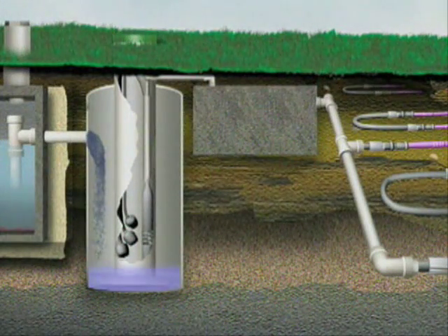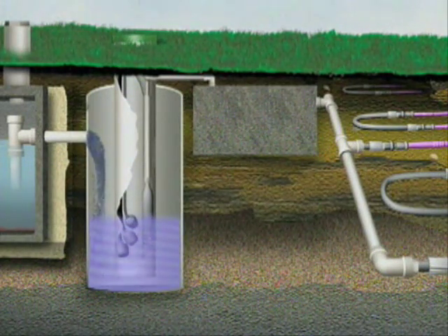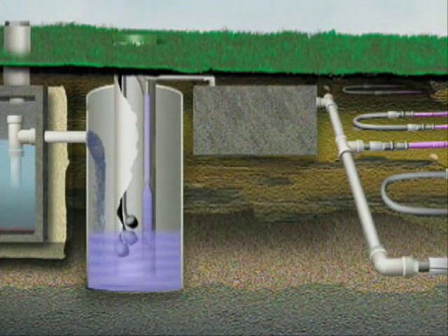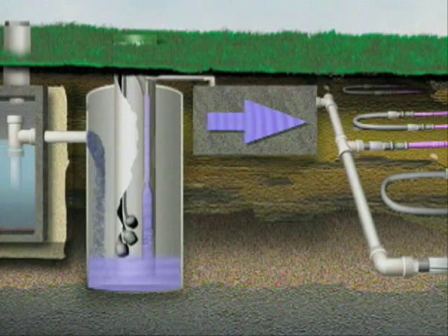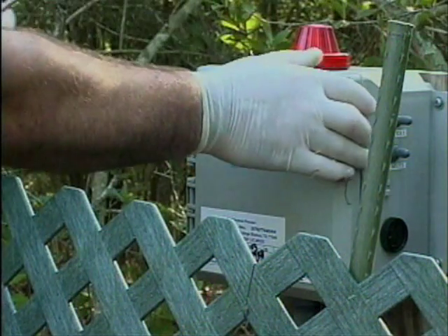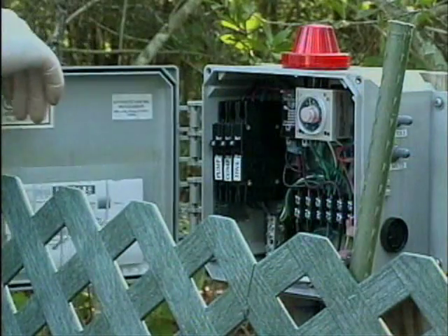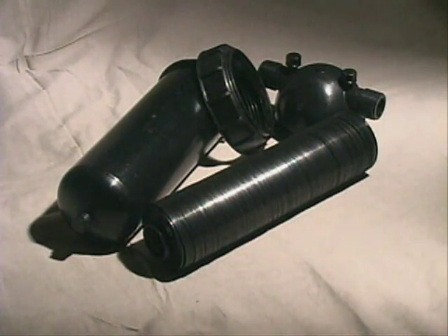Effluent leaving the pre-treatment device is stored in a pump tank until it is ready to be dosed into the drip field. Typically, a high-head pump pushes the water through the filtration device and into the drip dispersal system. A control system monitors the operation of the system and doses the wastewater into the field. The filtration system removes large particles that cannot pass through the drip emitters.